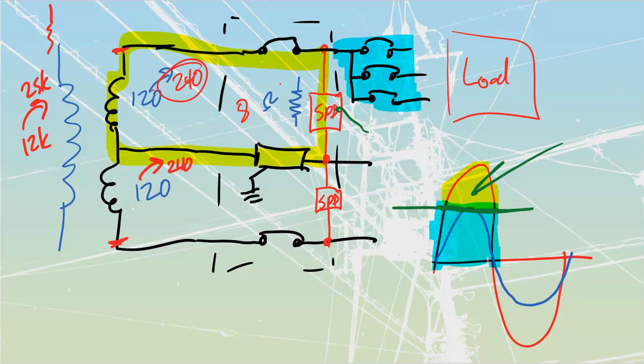It's really good because it can drop so rapidly and it can dissipate so much. But as soon as it goes to low values, it will not maintain our system voltage over top of it. So all of these loads over here are going to get browned out. Brown out is simply where my voltage drops away. So you just see that off of them. You get the strike. The strike doesn't go through, but everything does shut off and has to come back on. It's annoying, but it's better than stuff blowing up.